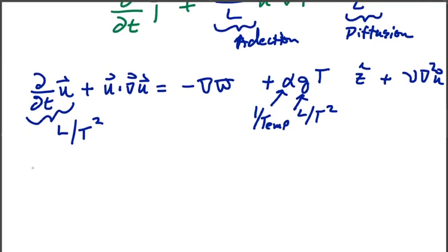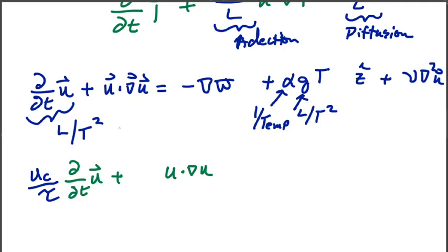All right, let's now non-dimensionalize this. So as we collect our terms out front, I'm going to leave u characteristics in here for now. I'm not going to use our lemma until a few moments from now. We've got d by dt non-dimensional of u. We've got our u dot grad on u, and we've got the term u characteristic squared over L as our dimensional component.